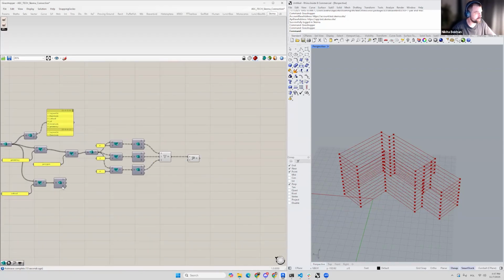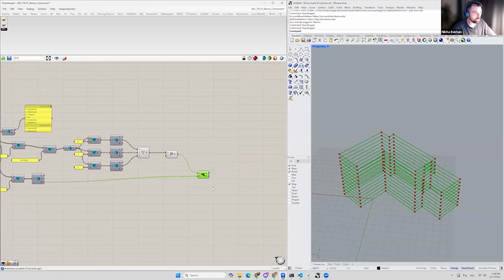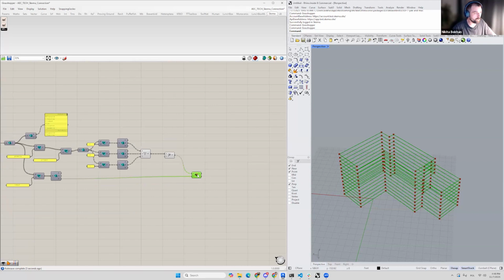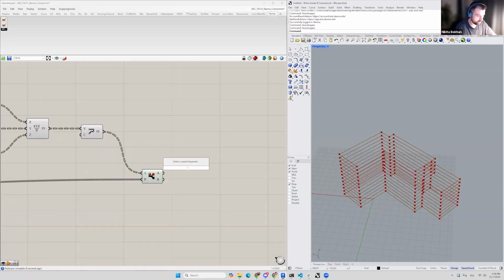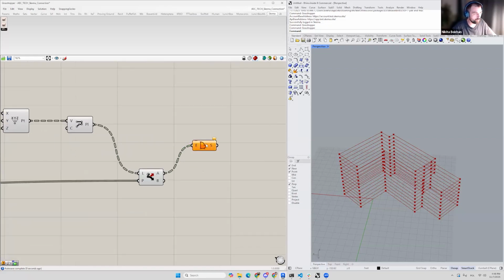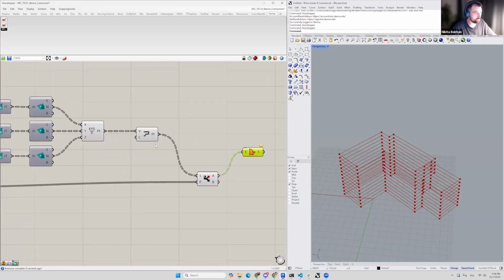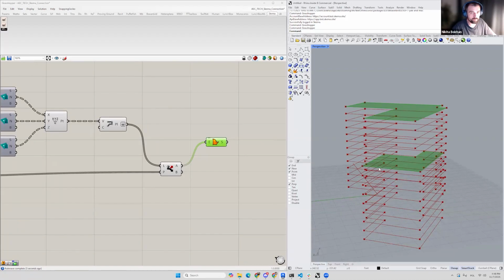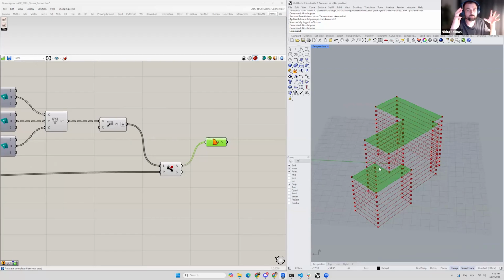And essentially, this is the map based on which I now can use the Patch component and simply use the Boolean value as a pattern. And now I can list all my polylines. When I create a boundary surface, I need to flatten the list with all the polylines to make it visible. So as you can see, right now I have only slabs, which are actually curves.